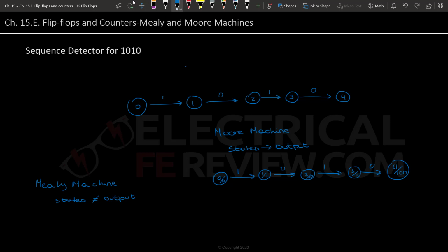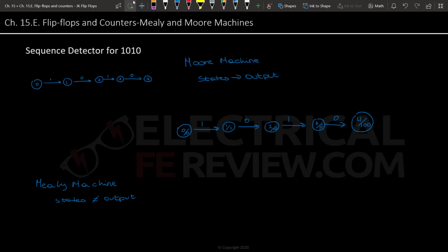So now let's look more into this Moore machine. I'm going to move our initial thought design so that we have more space to work on the Moore state diagram. So now we have our basic idea for the sequence. However, we are forgetting some possible inputs. For state diagrams, we always need to take care of every single possibility. So let's look into that. First, we're in state 0, and if we get a 0, we should stay in state 0.